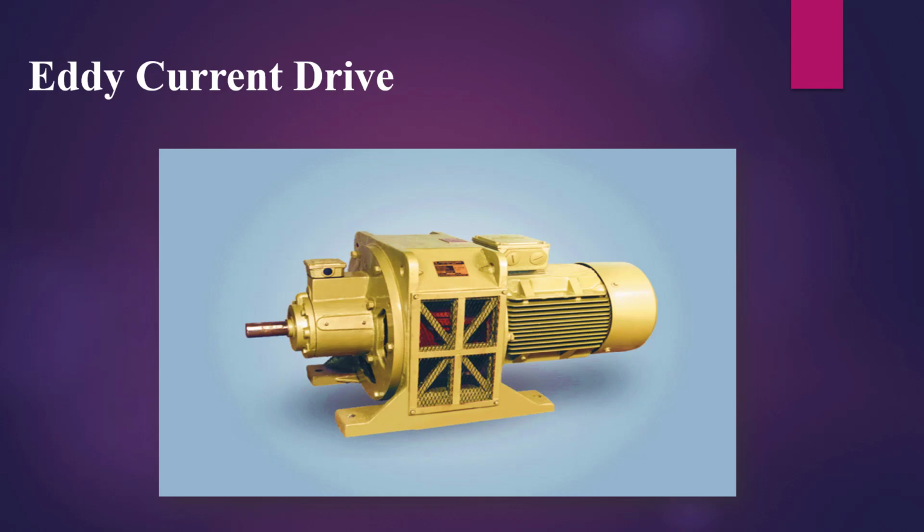Using the principles of electromagnetic induction, torque is transferred from a rotating drum, mounted onto the shaft of a fixed-speed electric motor, across the air gap to an output drum and shaft, which is coupled to the driven load. The speed of the output shaft depends on the slip between the input and output drums, which is controlled by the magnetic field strength.